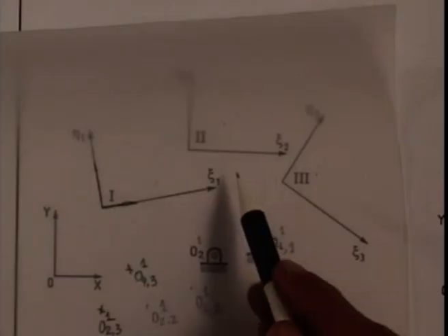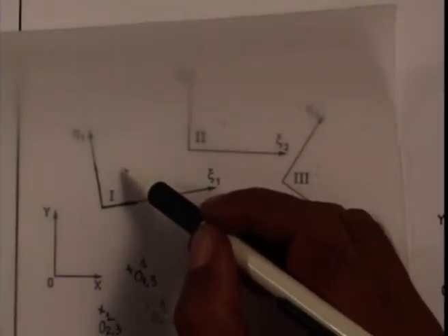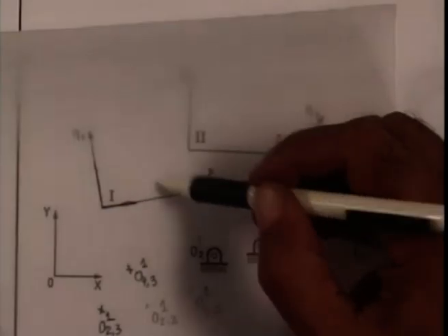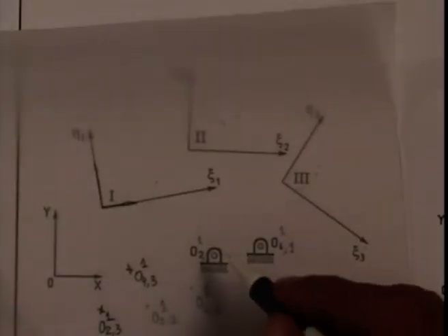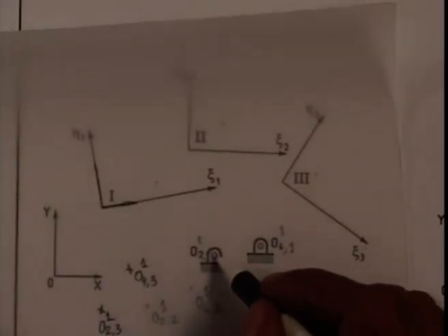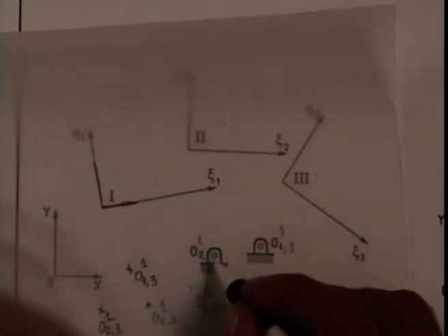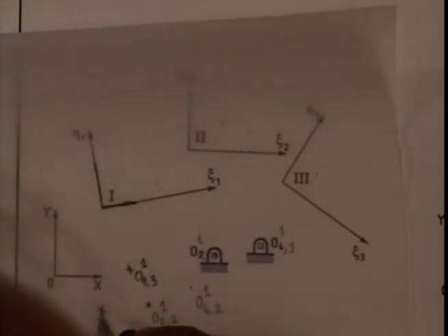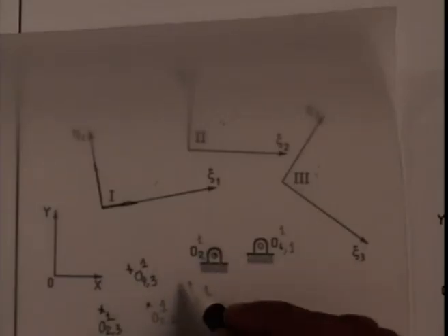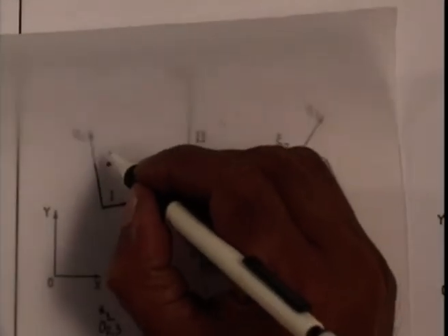If the coupler is fixed, then A does not move, A is fixed, and because the A O2 distance is the same, then O2 moves on a circle with A as center. So we have to determine the center of the circle passing through O211, O221 and O231. This is 1 point, this is 1 point, and this is 1 point. So it is very easy to determine the center of a circle passing through these 3 points, and that will be A1.